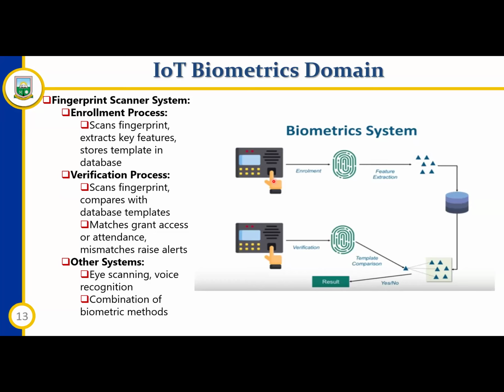Most times, the security experts usually don't go in for 100%, because there are times, maybe during the enrollment, we are unable to pick every corner of the finger, possibly the right index finger. So if you use 100% and even the finger is a little wet or whatever, the threshold is 100%, you can imagine that the person might be standing by the door trying so many times and not getting access, because the access threshold that was given is quite high.